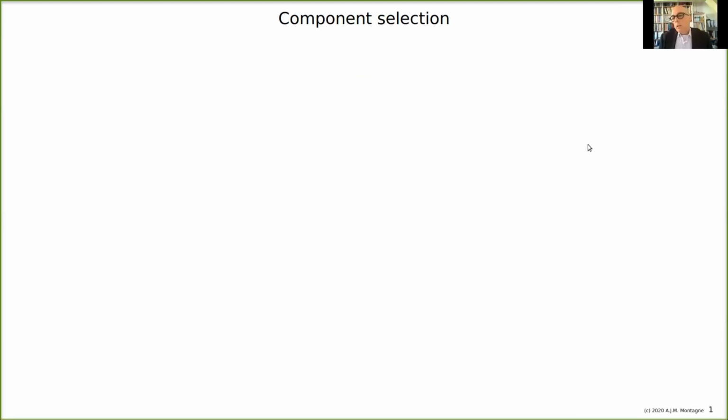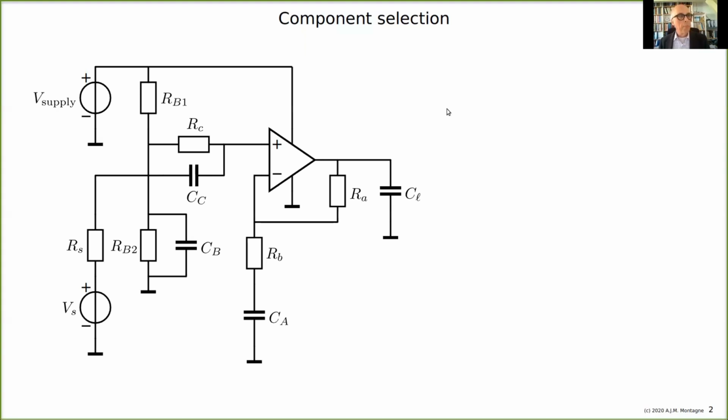I can only make the model of the amplifier more complete if I did some selection. And I already have a lot of things to look at. I have an output voltage range and a swing that I need. I need almost a rail-to-rail output operational amplifier. I have a gain bandwidth product. I know about its noise. I can calculate the showstopper value. So we are going to select components and put it in this diagram.